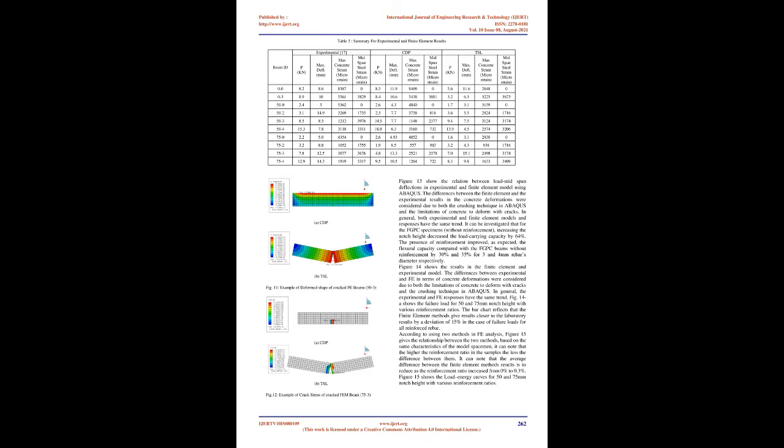Damage for traction separation laws model, TSL. Abaqus allows for the modeling of an adhesive layer using the traction separation law in order to allow for the debonding failure mode. Abaqus provides two techniques for this purpose. The first is by using a cohesive element, and the second depends on using a surface-based cohesive behavior. The fracture energy is equal to the area under the load deflection curve. One can identify the fracture properties as the cohesive interaction and choose either a linear or an exponential softening behavior.